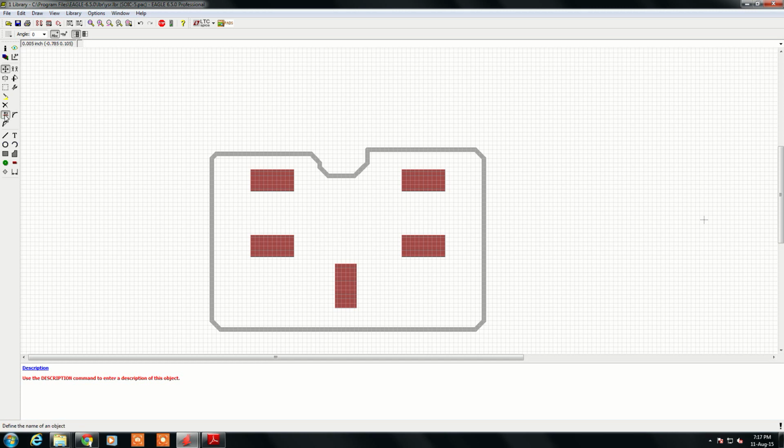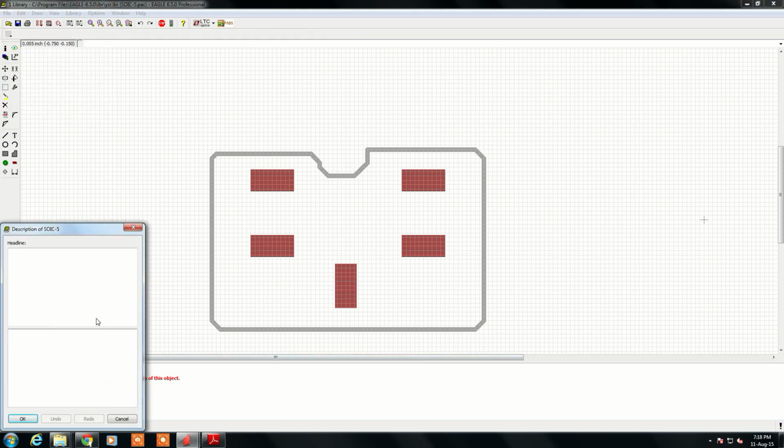And if you want to give any names to the pads, you can. Right now the pads are P3, but the names have no meaning because we don't draw the lines on the layout side. Usually we join the lines on the top side. You can also delete anything whenever you want, or use the undo command. You can use a text box to give some name, and you can also give a description about the package. Say for example, this is about the package, so you can say